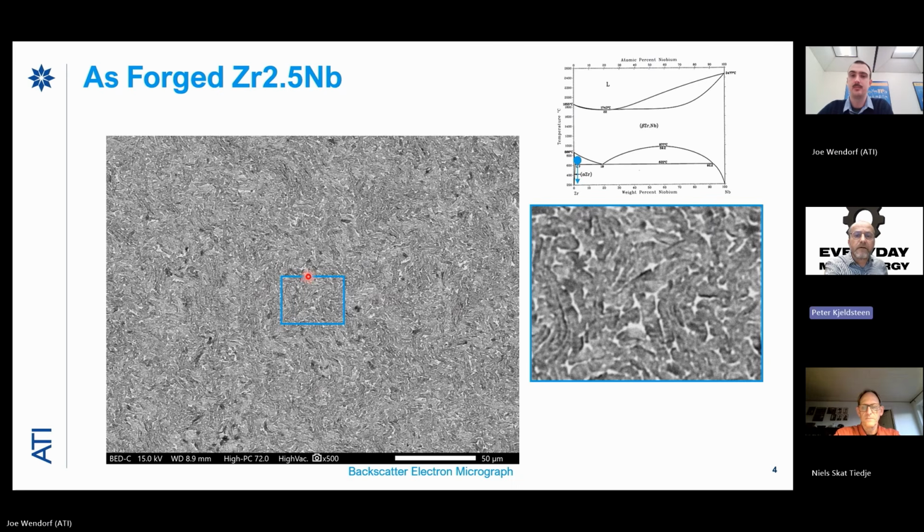alpha grains. I'm guessing when I look at the phase diagram, there's not a lot of segregation during solidification, but of course you will have these large columnar crystals. So homogenization should not be so complicated. Yes, homogenization is usually less of a concern than getting a consistent grain size and morphology.